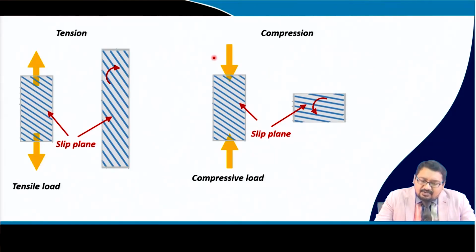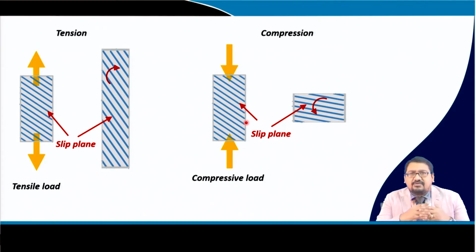On the other hand, in case of compression, what happens is that if these are the slip planes which produce the highest amount of tau RSS with the combination of the Schmid factor and the loading stress, then if this is the slip system which is the primary slip system, the plane will start to rotate away from the compression direction, and the plane normal will start to go towards the compression direction, and the direction in which the slip is taking place is also going away from the compression direction, and this leads to the evolution of texture during deformation, right. So, this is quite simple, right.